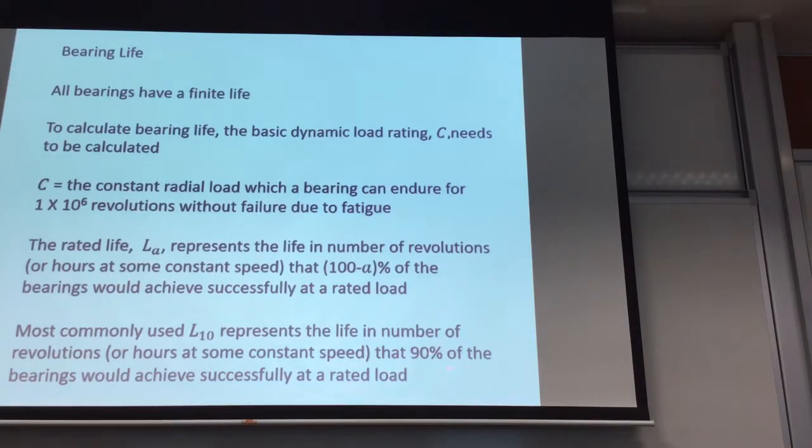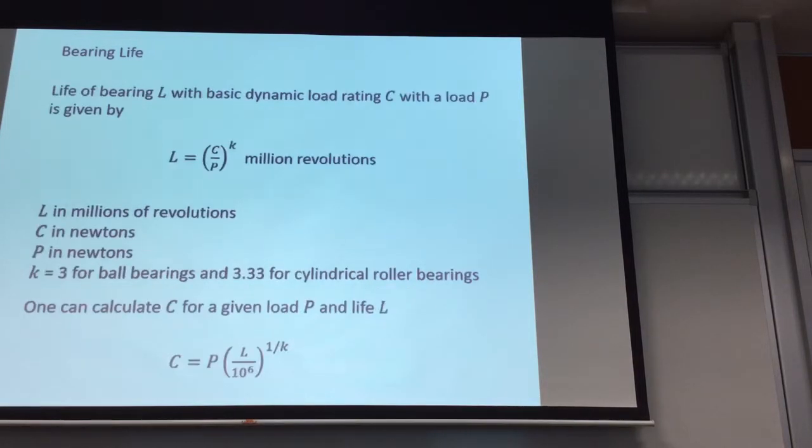So if you want 90% of the bearings to achieve the life at the rated load, your L_A is basically given by L10. So L10 represents the life that 90% of the bearings will be able to achieve.